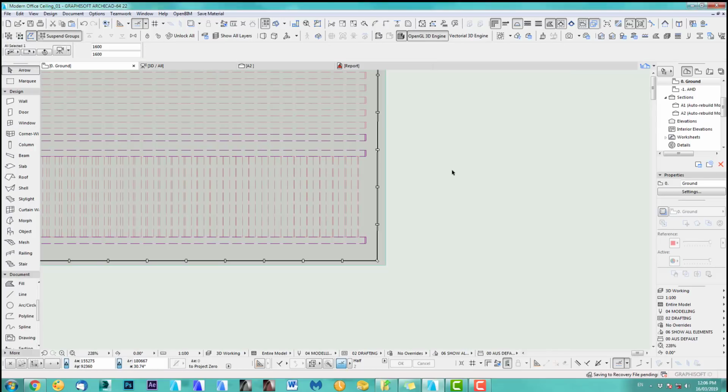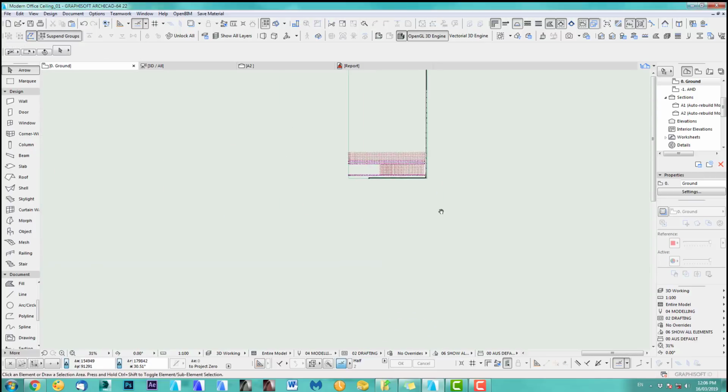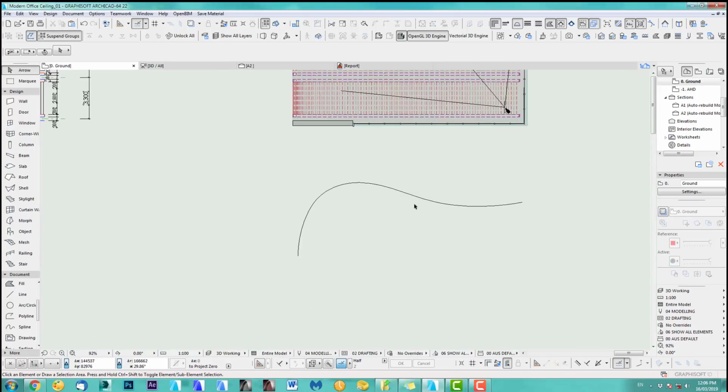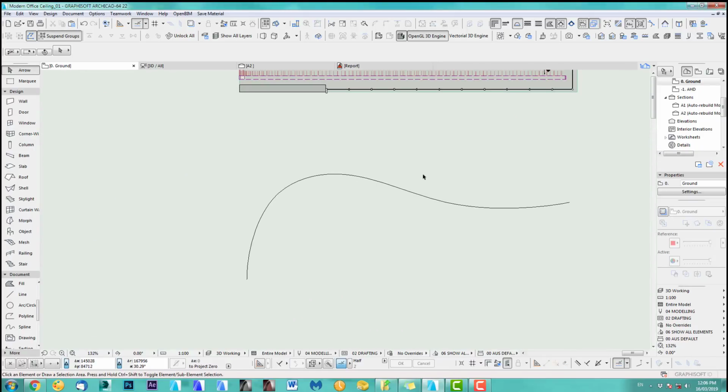That'll be exciting because there's a bit of, well, I call it cheat sweep, as we can't sweep in ARCHICAD, but I can show you how to get close to it. So, back to my spline. What do I do? How do I sweep now this light which has a round diameter along this spline?